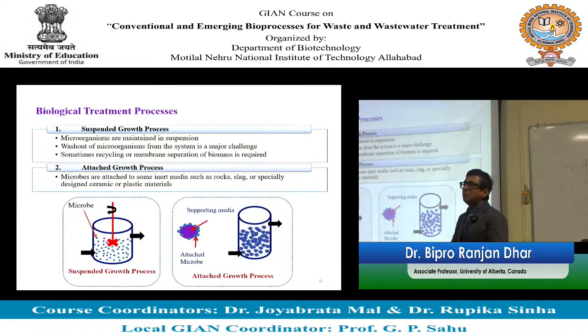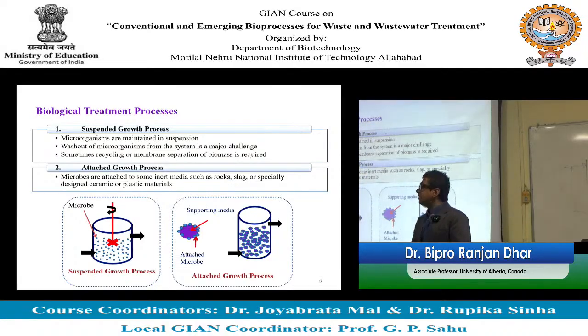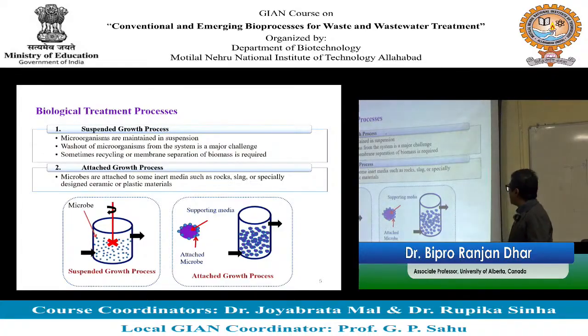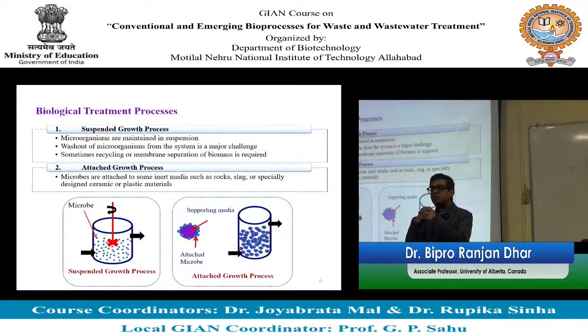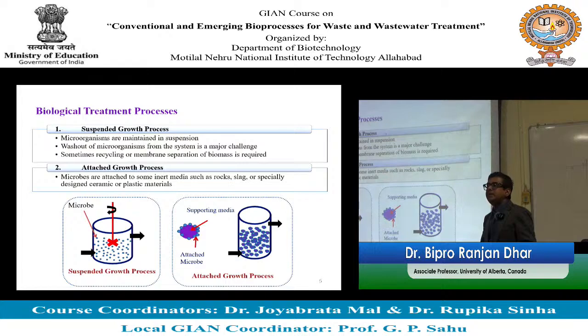Microbes are going to form biofilm on those inert media, okay. And when wastewater flows through the system, microbes and your organic contaminants are going to interact, and the contaminants are going to be removed in the process, okay. But because the microbes are attached to the media, they can be easily retained in the system, okay.